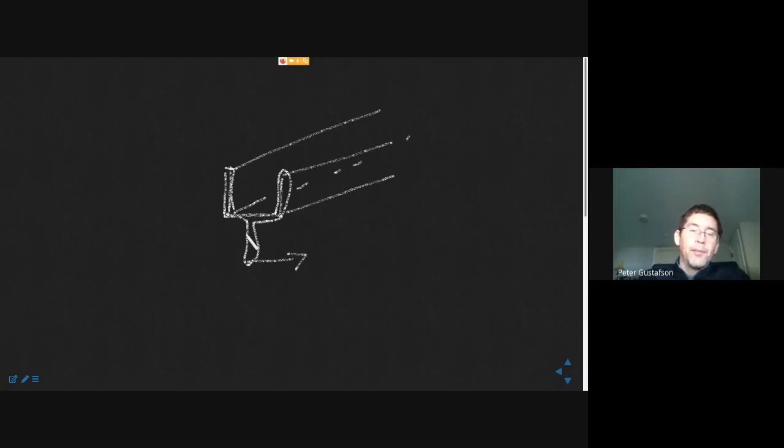So this is very much, honestly, like an airfoil. In an airfoil like this, you might actually only have one real rigid spar. And then the center of lift could be, say, here, and it's passed through ribs and skins to have a resultant on the cross section, but the actual beam that's carrying it is not the same. The rib transfers the load into the beam. You're not loading the beam directly. So Scott, does that answer your question? Does it make sense?